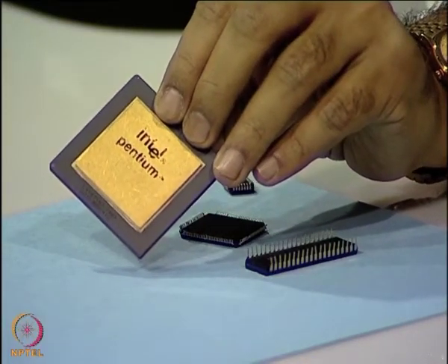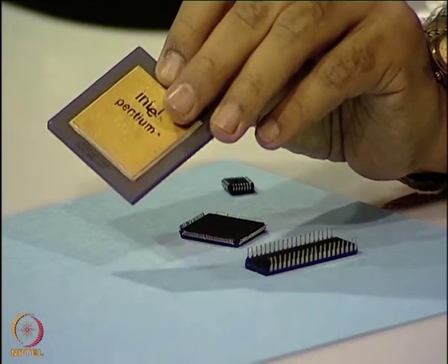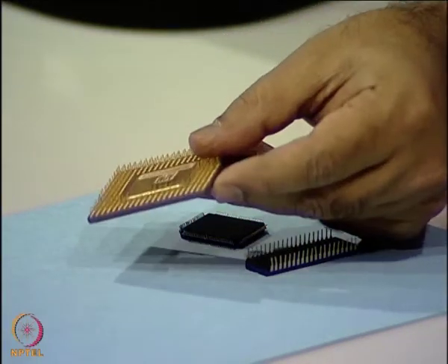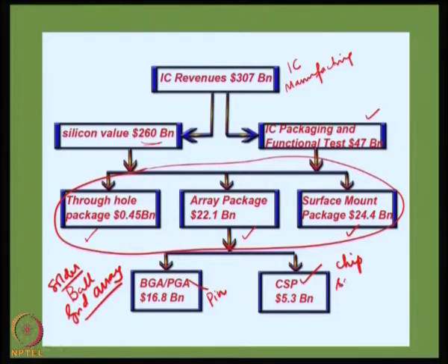This is an Intel Pentium processor, fairly heavy. This is completely packaged. So, if you take a cross section of this die, you will see the bare die interconnected, and finally, the IOs are in the form of pins. And finally, we will look at what is a chip size package. CSP stands for chip scale or chip size package. So, this chart that I am showing you now is fairly current. 20 years ago, most of us were using through hole packages. Today, we are into the area array and surface mount device arena, and that is how it displays a significant growth and miniaturization across products.